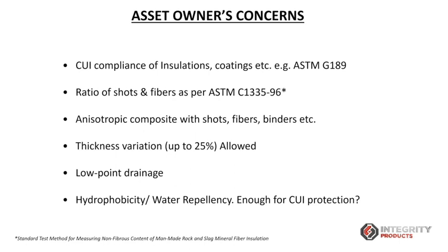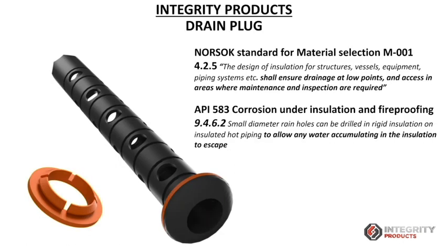And another thing is hydrophobicity. Do we think that the water repellency of the insulation is enough for CUI mitigation? We know that it's a great thing, but what about the 6 o'clock position, the low point drains and all these locations? It's even mentioned in the research paper that hydrophobicity is a concern, especially under immersion conditions. And we know that at the 6 o'clock position, the water is likely going to stay, especially if there is no drain plug or no drainage system within the insulation. I just mentioned the word drainage, or the low point drains in the system.